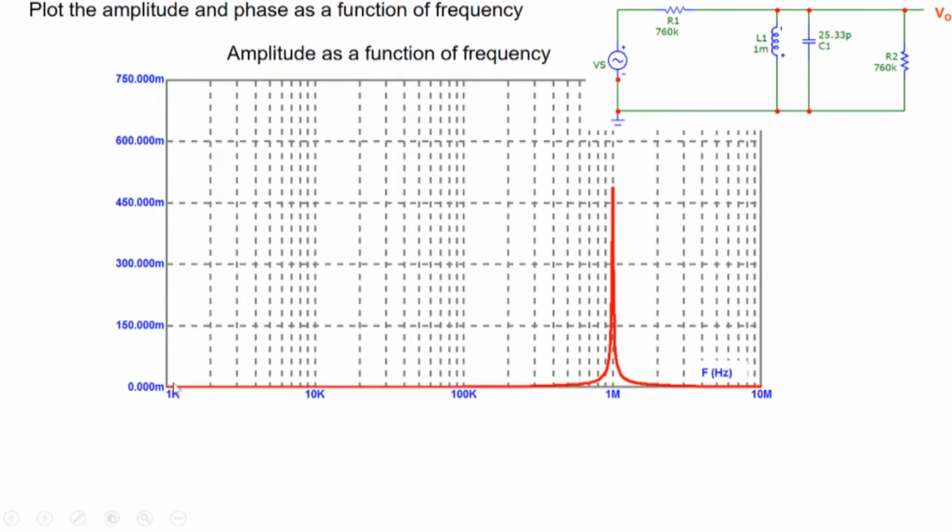So we see something interesting, which was not apparent while looking at the circuit in the time domain. We see that the amplitude of the output is very, very low. It's hardly anything, though the linear scale here doesn't really mean zero. All that it means is that it's very small here, and then the amplitude rises here and then falls again. So what we see here is we can understand the nature of the circuit. The circuit is highly frequency selective, right?